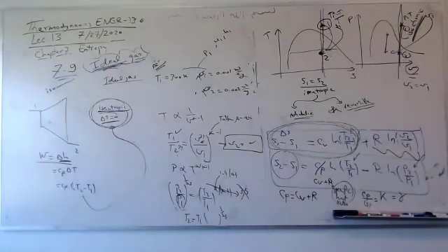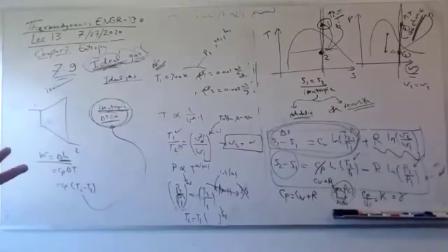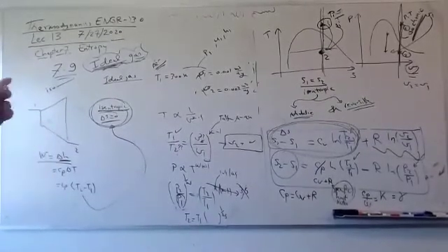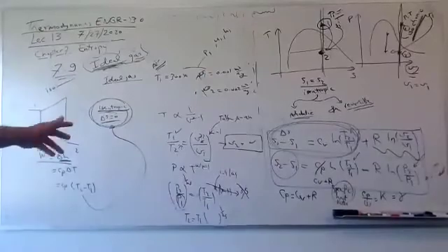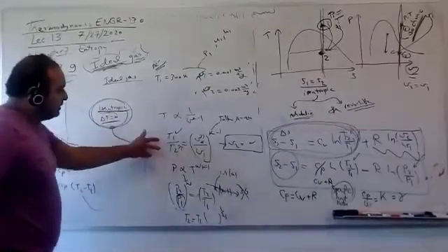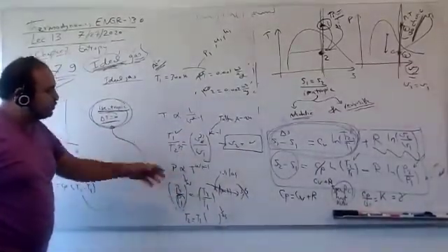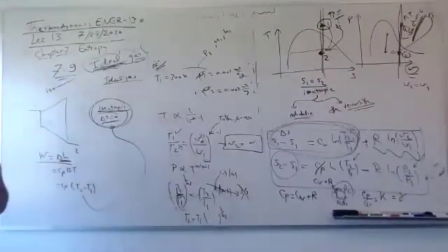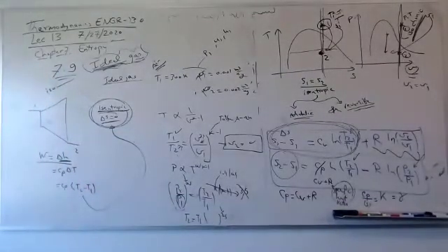So for isentropic, I don't need to give you two independent intensive properties. I only need to give you one, because you can use this pressure ratio, temperature ratio, or volume ratio to obtain the missing piece. Okay, guys? Does it make sense now?